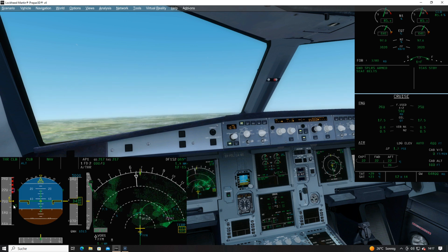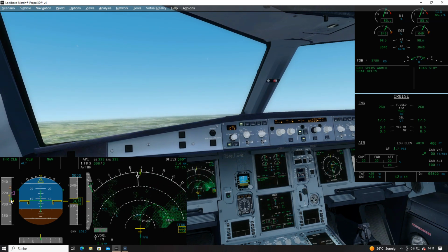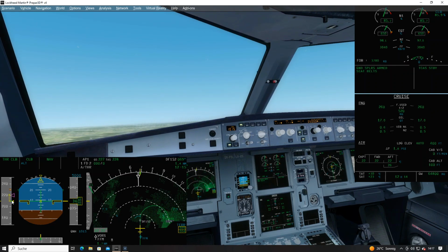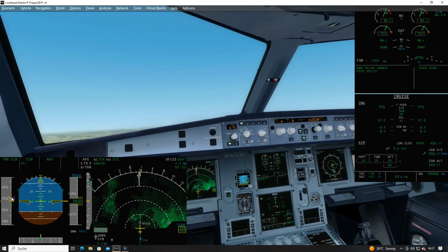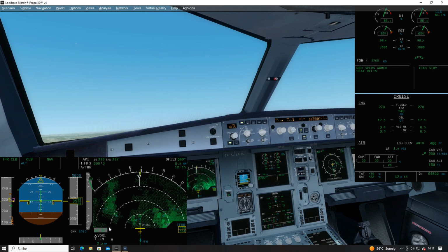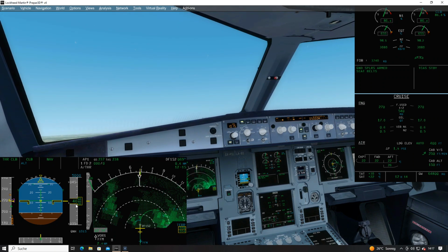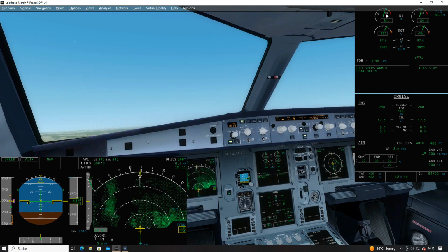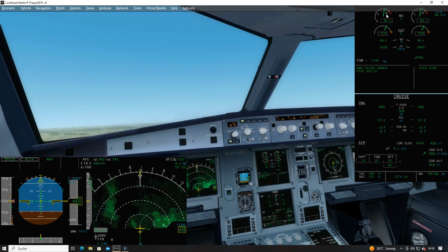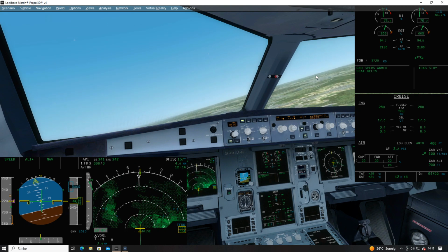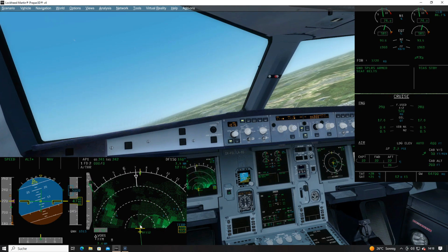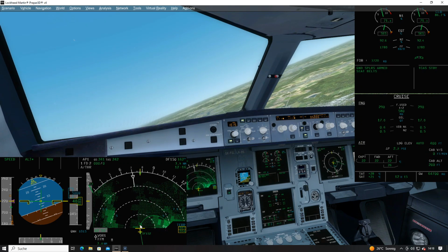Now we're above the speed and we retract the flaps. Green dot has now become active, so this is the minimum maneuvering speed for clean configuration. Speed is 220, that's a requirement of the departure route for the first turn. Rate of climb is high, so 4,000 feet passing. Alt capture mode, the star mode, is now active. Thrust is starting to reduce. You can see it here on the engine display because we're approaching the altitude. And the aircraft starts to bank, starts to turn with a right turn on the departure route.